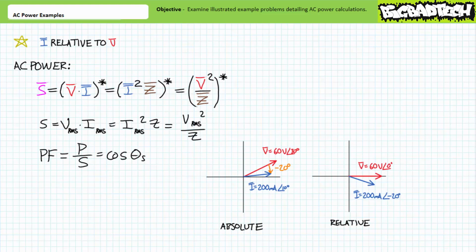A related figure, power factor, is the ratio of real power over apparent power. A simple algebraic rearrangement of this equation demonstrates that real power equals apparent power magnitude times power factor. Used in this manner, power factor is in effect a cheat code that extracts the real power component from apparent power without the use of complex numbers. Power factor is often a pre-calculated quantity that is written directly on a motor nameplate.